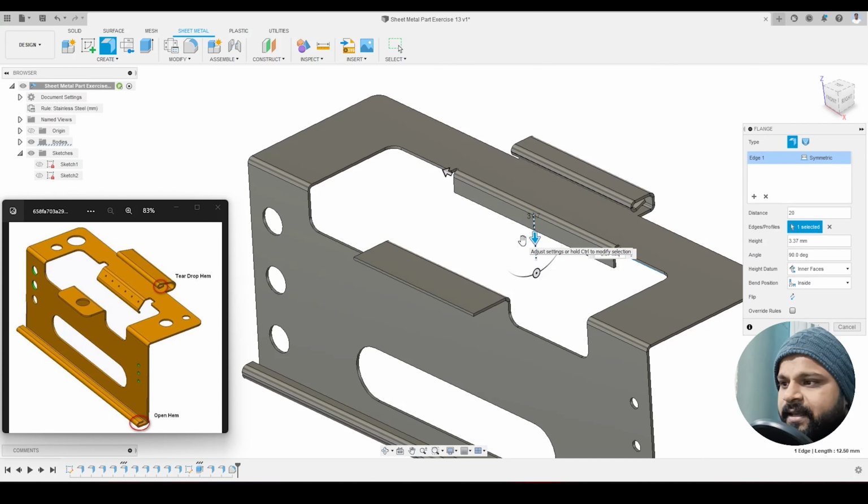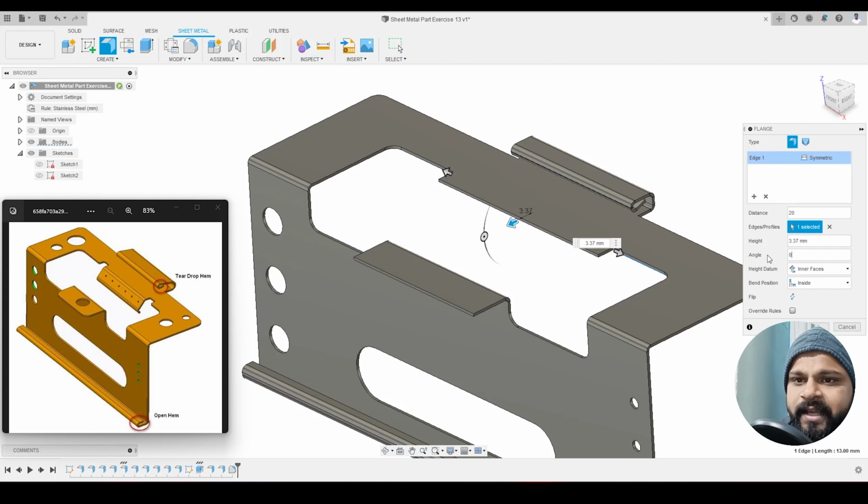Here you can see, right now from the image it's first extended a little bit forward, parallel to the edge. So here I will just make it 0 degrees and make it about 2 millimeters extended towards the edge, parallel to the face, and we'll press OK.